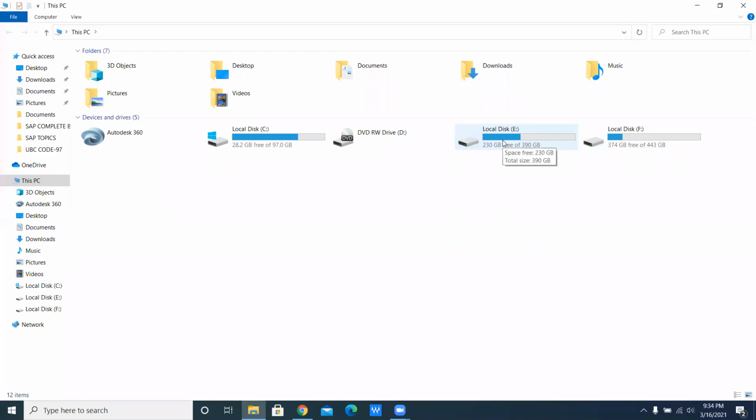Okay, from SAP there are its own factors: importance factor, modification factor, seismic response factor, eccentricity ratio, and CT, which is called the time period. So there are different types of things you can get according to your code. Here my code is UBC 97.